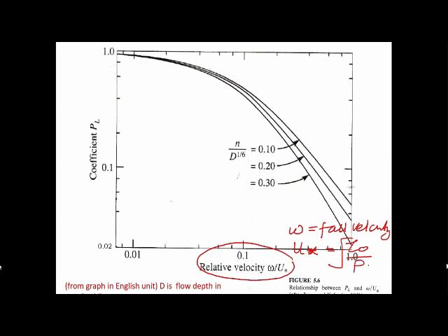Once you calculate that, you must also know your roughness, and your flow depth D. Sorry, your flow depth, not particle size, your flow depth D. Okay, don't confuse small d and big D. Sometimes big D is used, sometimes small d, and you have to know whether it is a sediment size or a water depth. But for Kalinske, the big D here is your flow depth.